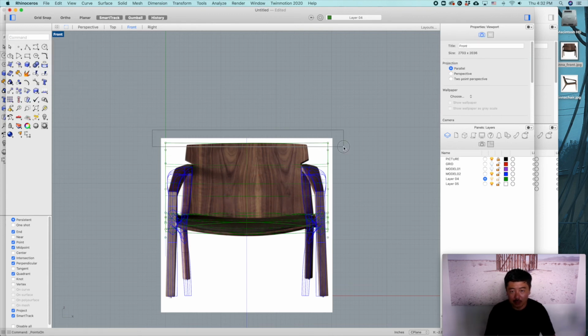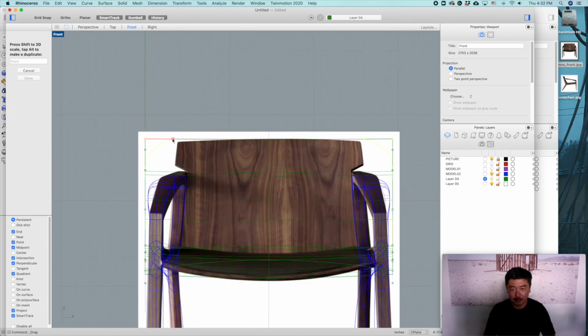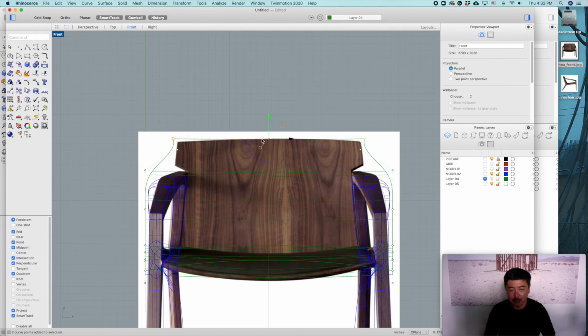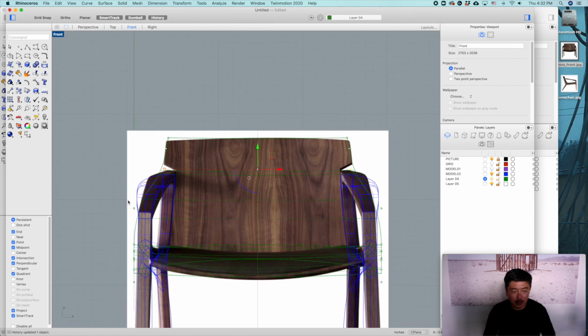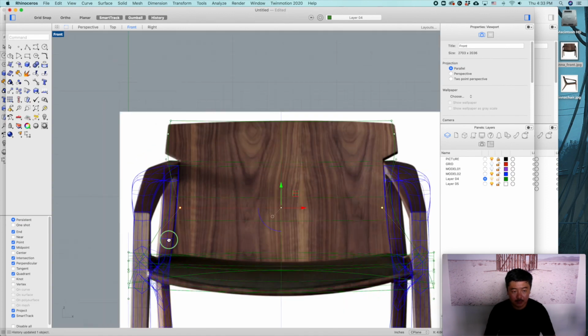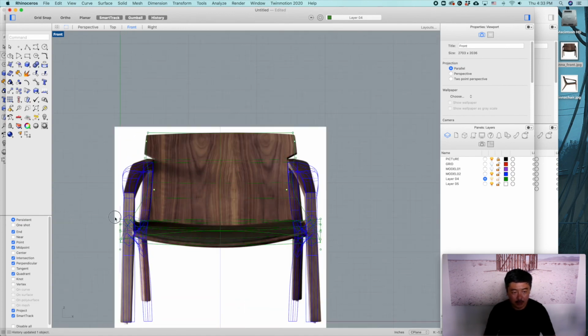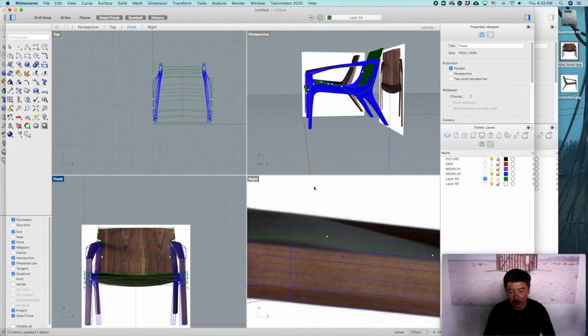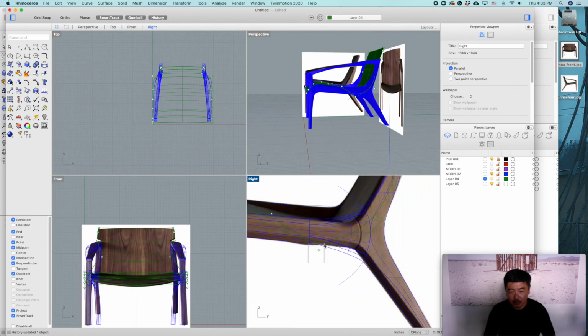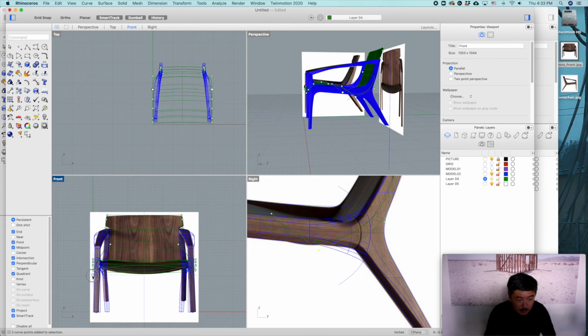And we have these control points. If you select both on the right side and left side and change the scale handle, it will let you scale on both sides. So that's going to be helpful for creating this kind of surface. Okay, and then you can take both sides of the curves and get them to be inside of the surface. Kind of hard to choose, so you can go to side view and select them, and then scale them in.